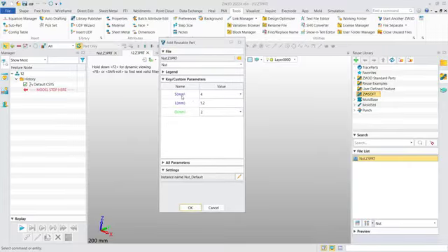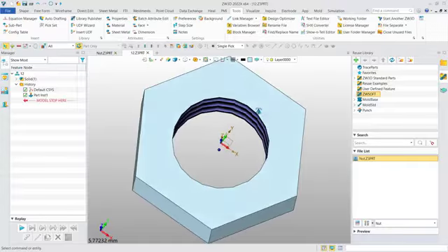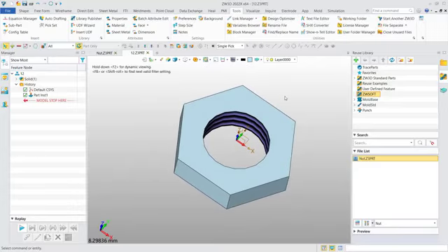And here you can see these two are the key parameters, which means we can only select values from the drop-down list. For the D, which is a custom parameter, we can manually type the value by ourselves. For example, we can change it to 3. Now we can click OK to insert. Select a location. Now you can see the insert has succeeded. Okay, this is the general workflow of creating a part library.